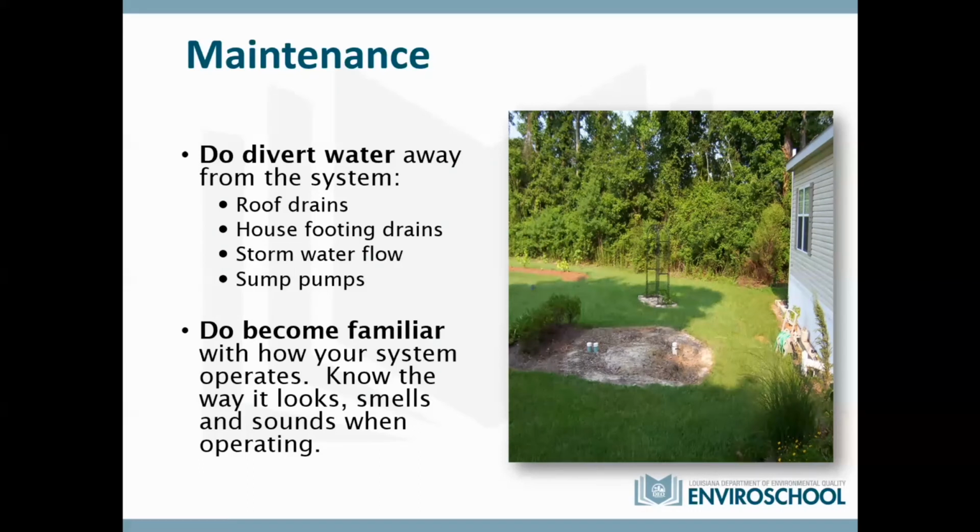But in basic terms, don't drain your roof water to your system. House footings, keep that away. Don't have any stormwater flow going into it. If you use any sump pumps, don't direct that flow to where your system is located. And again, I know we've said this one before, but become familiar. Know what your system looks like, what it smells like, what it feels like. Just be familiar with it.